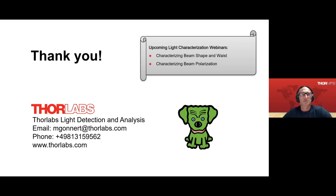One question going back to the calibration of photodiodes. Sabi is asking, how well does a calibrated photodiode's calibration hold up over time? Normally, as for any of the power meter sensors, we recommend a yearly recalibration.